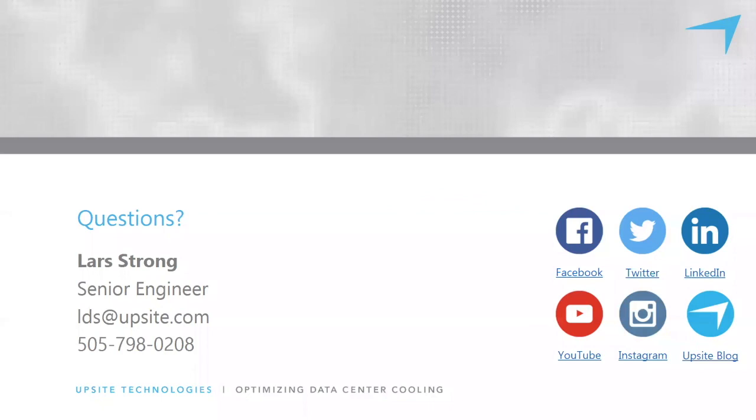And what I want to emphasize is that the goal there is 5 degrees Fahrenheit or 3 degrees Celsius for those other 2 delta T's. The air temperature should only drop 5 degrees from the time it leaves the server, on average the average exhaust air temperature, to the cooling unit, and the air temperature from the cooling unit to the warmest inlet of IT equipment. The goal is to be 5 degrees.